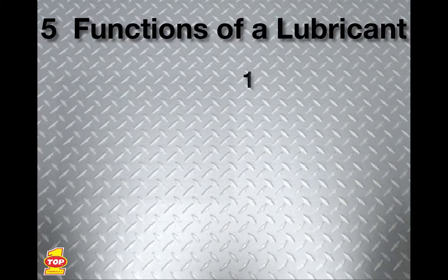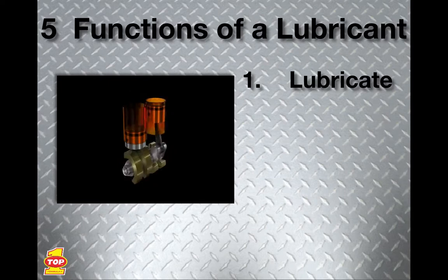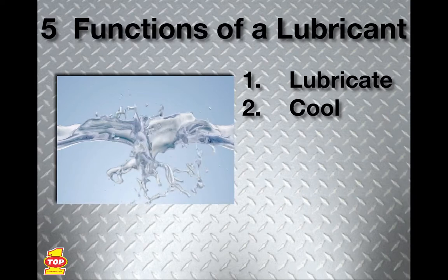Motor lubricants have 5 main functions in your engine. A lubricant should lubricate all moving parts of the engine to minimize corrosion and wear. The lubricant should cool the engine by carrying heat away from the components to keep it running effectively.